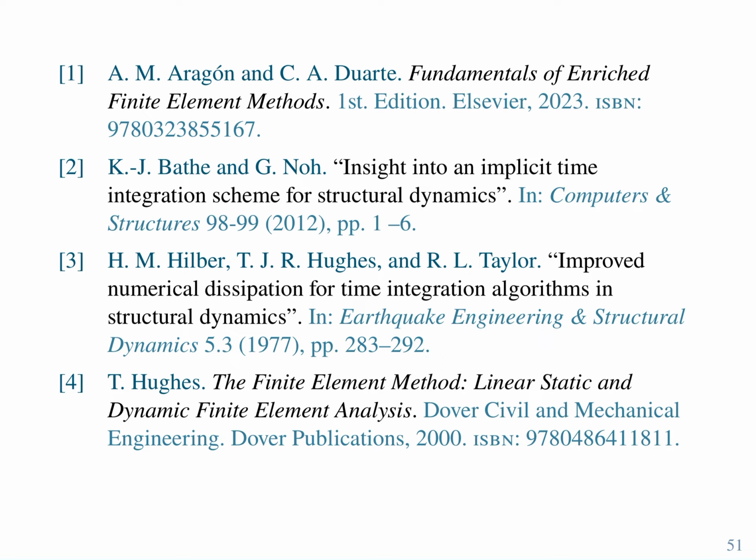Well, something I teach in my finite element course is that if you see something that doesn't work, if you see some weird chaotic behavior, we just apply common sense. What is the simplest problem that has the same behavior? You have to reduce the complexity of your problem, because if the simulation is already way too complex, it is extremely hard to find out what is wrong or where you have done something wrong. So maybe your system is chaotic by definition. There are chaotic dynamical systems, obviously, but maybe it is not.